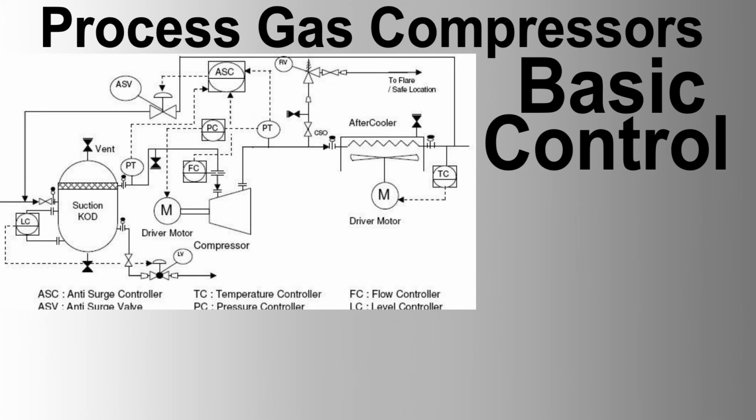6. Process side integration. A. Process measurements. Pressure transmitters (PT) measure suction and discharge pressures. Flow transmitters (FT) measure gas flow rates. Temperature transmitters (TT) measure gas and compressor temperatures.